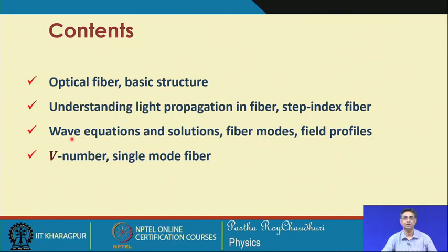Then the waveguide wave equation and its solution, which we will discuss for step index fibers, will lead to the fiber modes and the field profiles. A very important parameter is the V number, which we have discussed already in the context of planar optical waveguides, but here we will again define a similar quantity which gives all the specifications of an optical fiber. Then we will look at the condition under which a fiber will act as a single mode fiber.